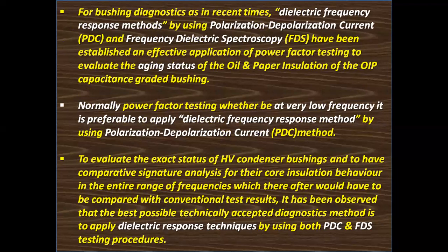For bushing diagnostics, in recent times, dielectric frequency response methods by using polarization or depolarization current and frequency dielectric spectroscopy have been established as an effective application of power factor testing to evaluate the aging status of the oil and paper insulation of the OIP, that is oil impregnated paper bushings, capacitance graded bushings.